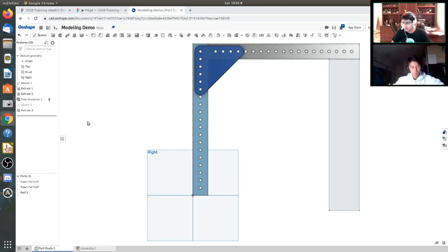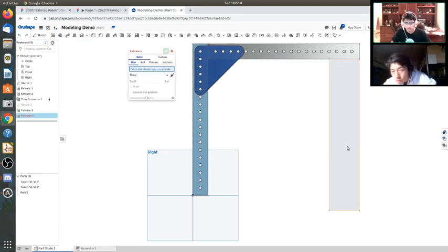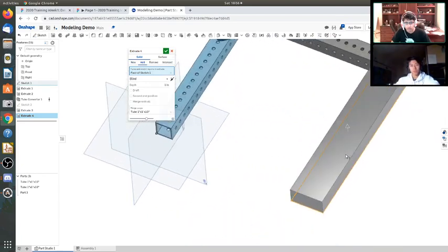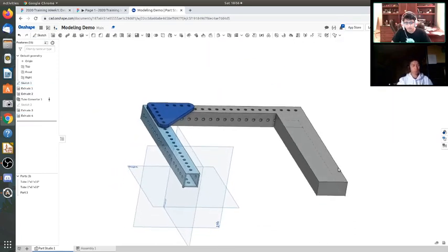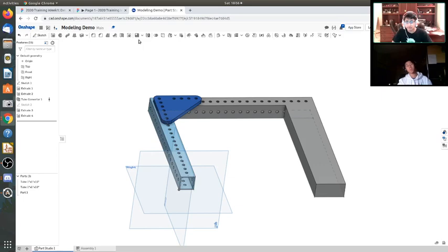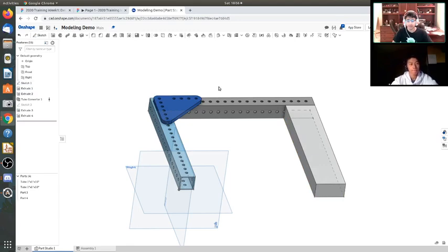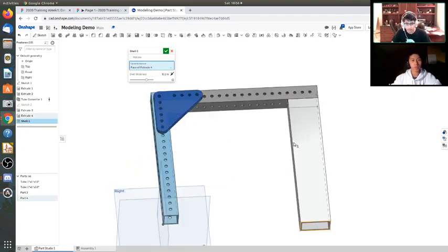How did you make it 3D? That's a great question. This is going to be covered in the Onshape pathways that we're having for homework. What you do is essentially click on this using the extrude feature, and it makes this. Then there's a feature script, which is a script somebody wrote. A feature script is essentially a programmed CAD tool that automates parts of CAD. But the manual way to do this would be to use the shell feature, which hollows out a face.